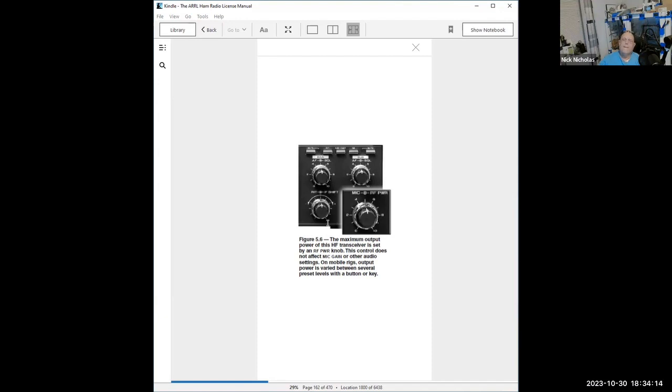Okay, now I'm going to talk about a couple other knobs here. One of them is called an RIT. You won't use this in FM, but you will when you get to HF operations a lot. You won't use it much otherwise. RIT allows you to shift where you're listening when you tune, so that if you have multiple people you're talking to and one of the guys is just off a little bit, you don't change your whole frequency. You just change the receiver on him. When you transmit, you'd still be on the same frequency you're supposed to be on, in case you forget to turn it back after he's done talking. So it gives you a little bit of a fine-tune adjustment on the receive frequency.